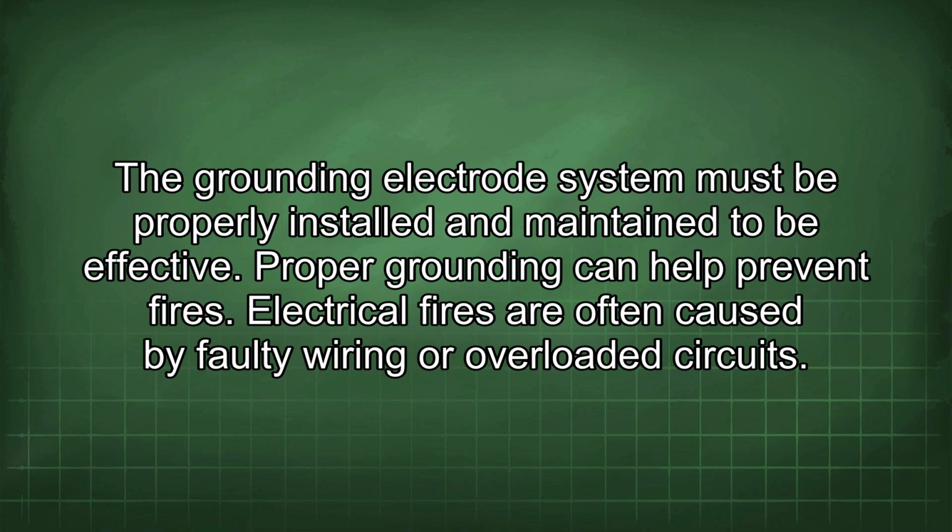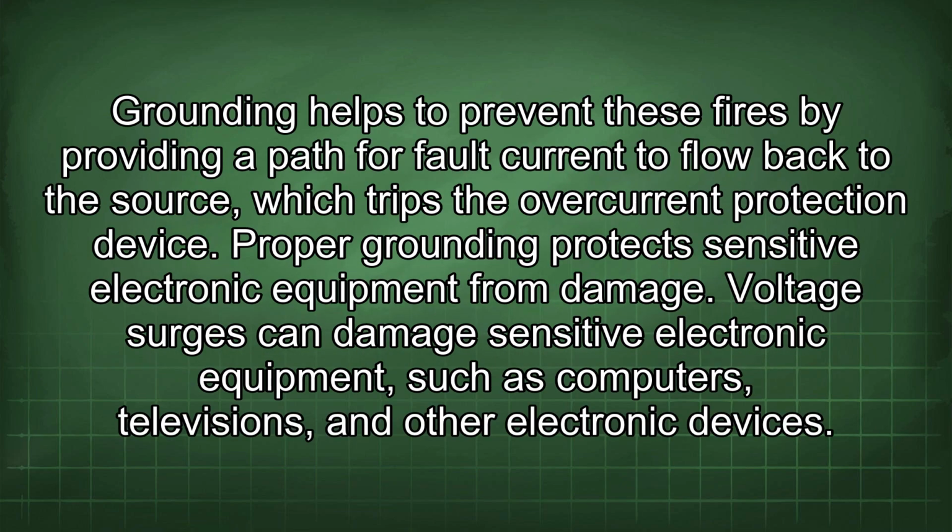Proper grounding can help prevent fires. Electrical fires are often caused by faulty wiring or overloaded circuits. Grounding helps to prevent these fires by providing a path for fault current to flow back to the source, which trips the overcurrent protection device.